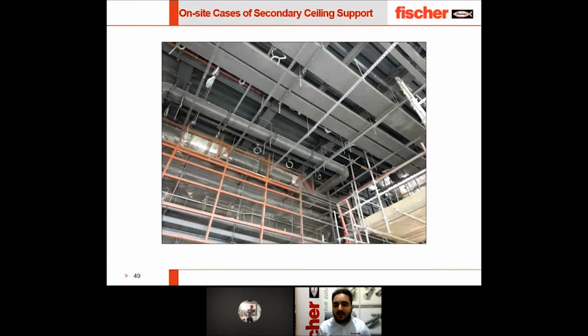Okay, what is the fire rating for your system? The steel itself is fire rated. Also, one of our ranges is fire stop. We can provide you the fire stop at the joint of the ceiling, at the joint of the top of the wall, when you have a gypsum board or different joints. We also have the fire stop material, fire sealant.